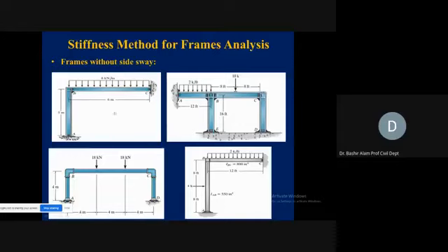We are not looking at the loads now. We are not looking at the geometry, just support conditions. It is giving you enough condition to declare this frame as a frame with outside sway, or a non-sway frame. Now coming to the right, why do we declare this a non-sway frame?